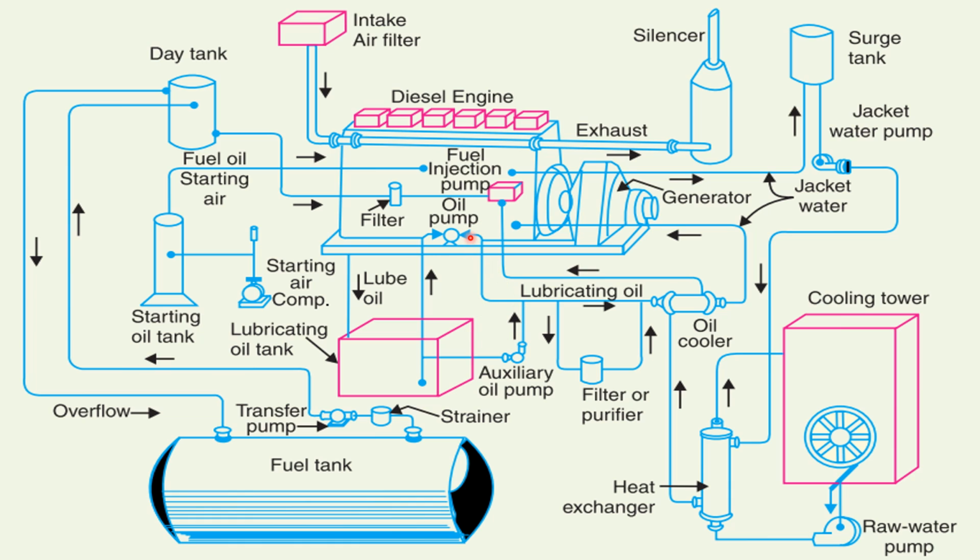Then this lubricating oil flows inside this diesel engine, and then from this diesel engine, this lubricating oil is sent into the filter and purifier to remove any particles which might have entered it during lubrication of the engine, and it is then sent into the oil cooler to be cooled and resent back into the engine.